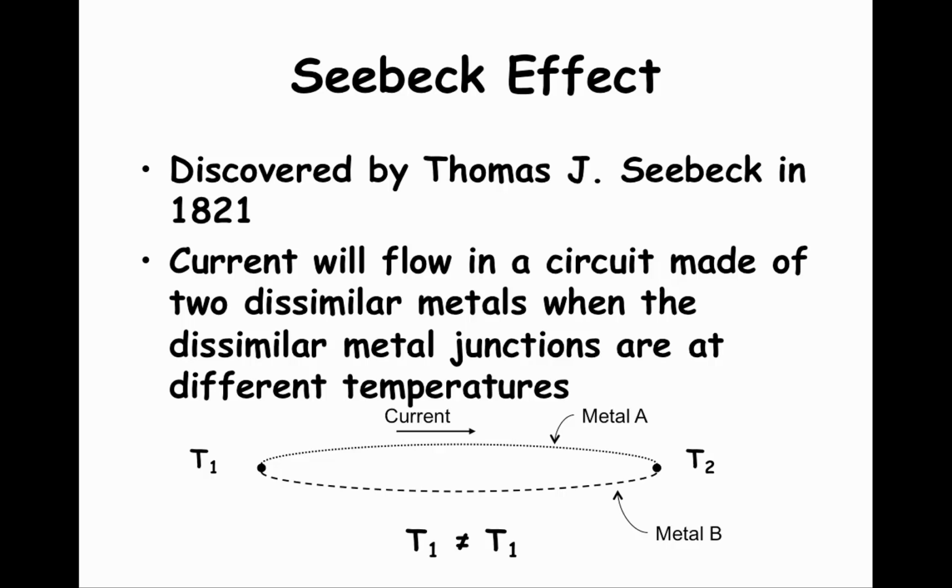Let's begin with a bit of information about the physical principles behind thermocouples. The first principle is called the Seebeck effect that was discovered by Thomas Seebeck in 1821. He discovered that a current would flow in a circuit made of two dissimilar metals when the two dissimilar metals junctions were at different temperatures.